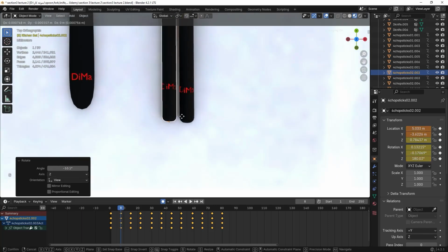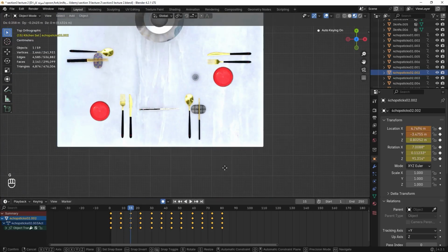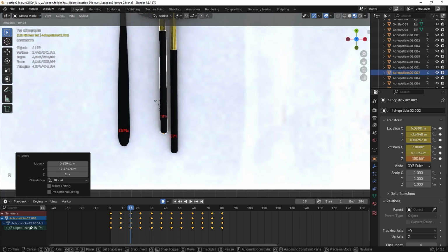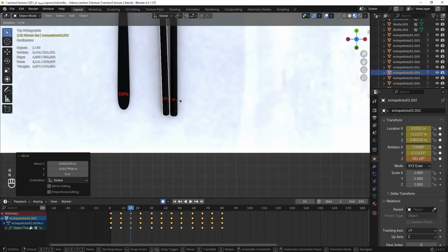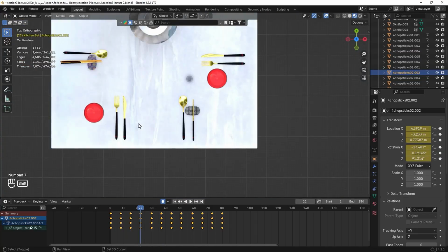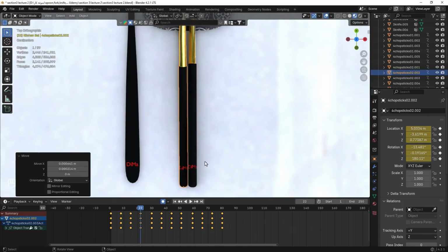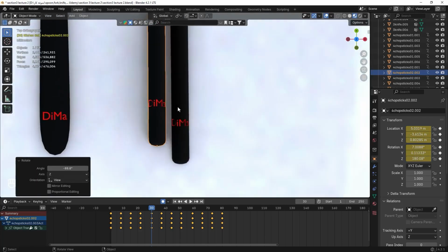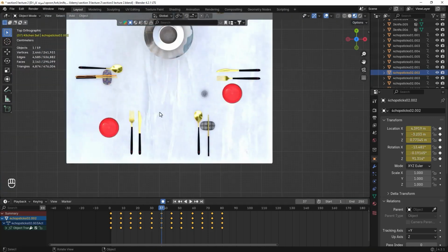And then we place the playhead on frame 15, and then by pressing the R key we rotate it almost 180 degrees and set and fix it on the holder in the right place. We also do this method and movements and rotations for frames 22, 30 and 37 in the same way as before, and then we delete the